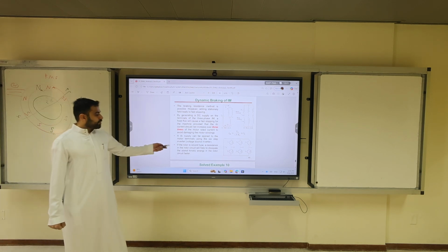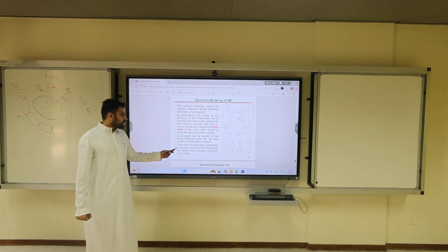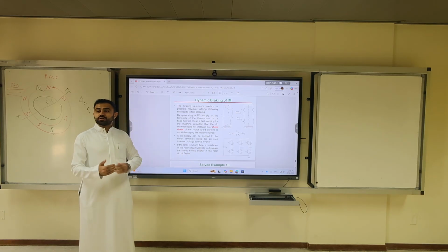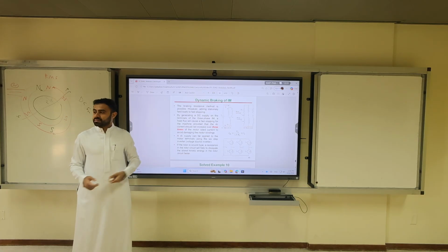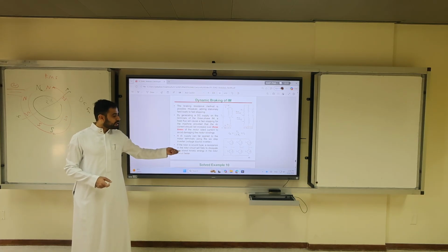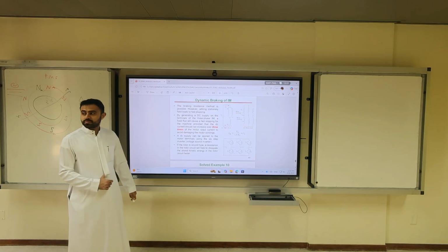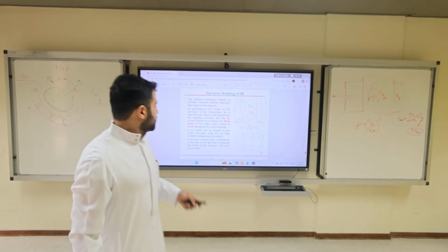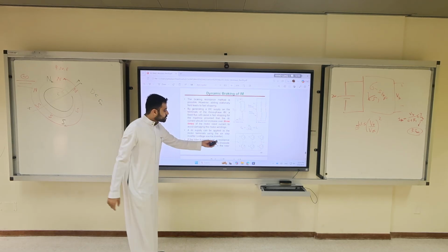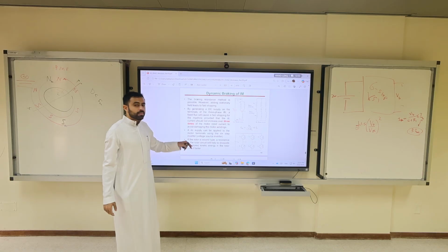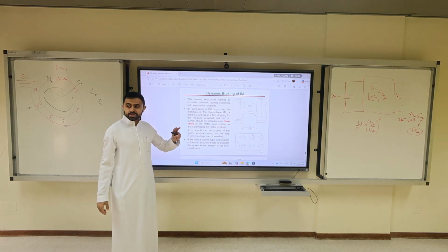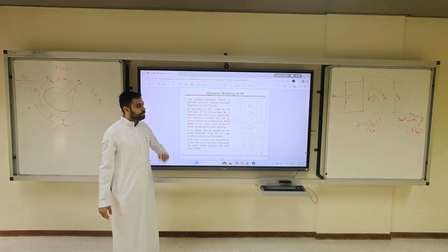So if the rotor is wound type, a resistance in the rotor circuit will help to dissipate. You can also merge both of them. You can have resistor and field in the wound rotor. This will be even faster with minimal losses.